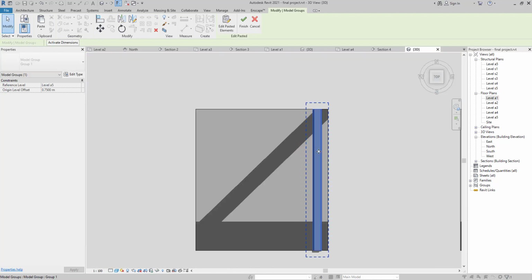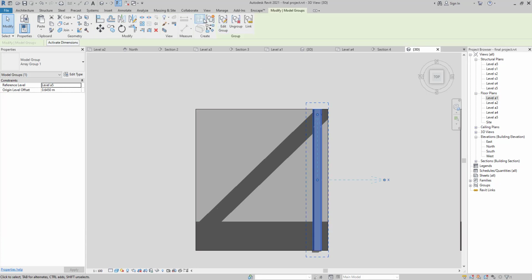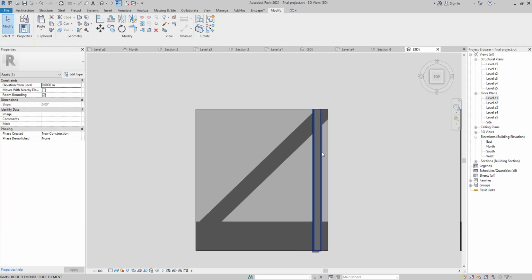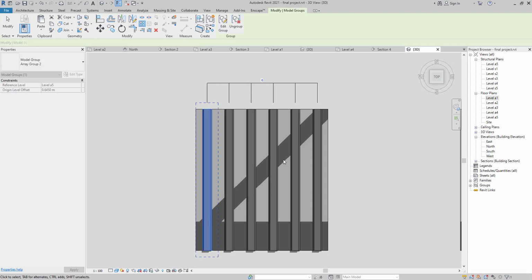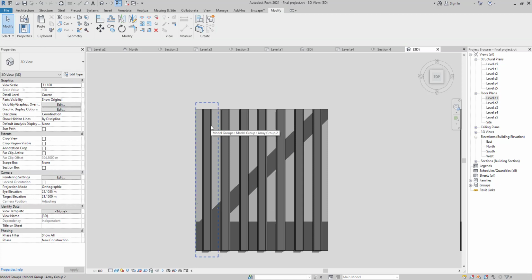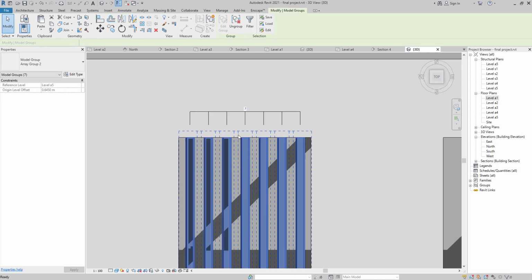So when I grab it here, I move it here, and after that I'm gonna go, for example, to my array system again, but I need to finish the group, or I can just ungroup this element, and after that I'm gonna use the array modifier here from the last option to create it here, put a value of 6, 7 works better, and after that I'm gonna grab them and use Ctrl C, Ctrl V.